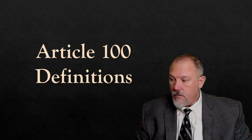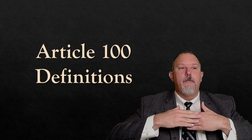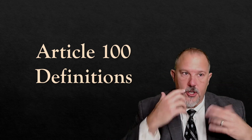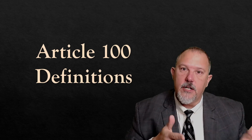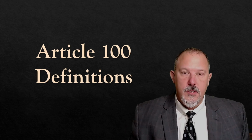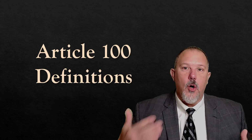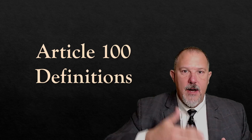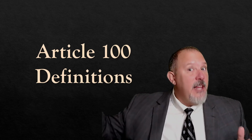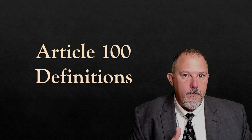So an overload is when I am overloading the circuit. Let's talk about a conductor's ampacity. If my conductor's ampacity is 20 amps and I'm at 25 amps, I am in an overload situation. My current is not significantly greater than the rating of that circuit.